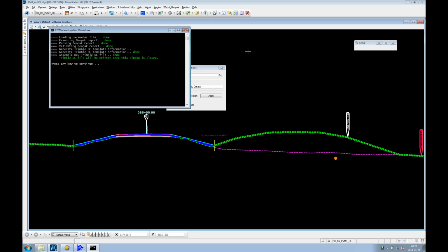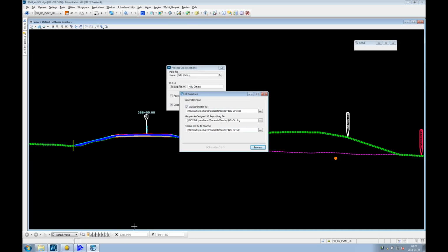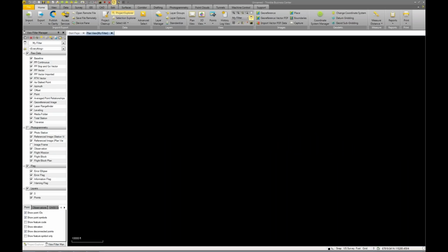While Andrew's doing this, he's using the DC file here and this proprietary, in-house software pack to get the data from the Bentley environment to the TBC environment. There are existing support for other formats. The DGN can be imported into TBC natively. iModel construction DGN, ICM.DGN can be supported and read into TBC as well as DXF or the old trusted DC file like Andrew's doing.